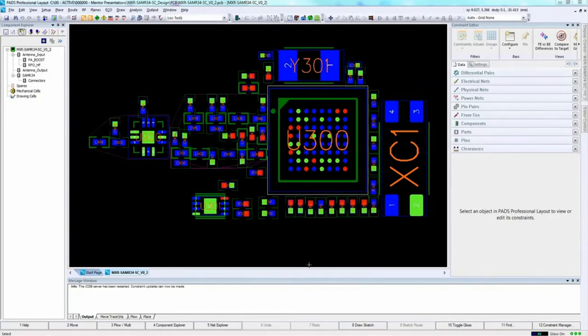You want to clarify the minimum width, separation, and height of a trace with the PCB manufacturer. What's the minimum distance between two layers? We covered that in our stack buildup. And what about the minimum drill and requirements of vias? Is it possible to use blind and buried vias? And would those choices be even permitted with your design, your target prices, and even if your board house can actually accomplish some of those mechanical requirements?